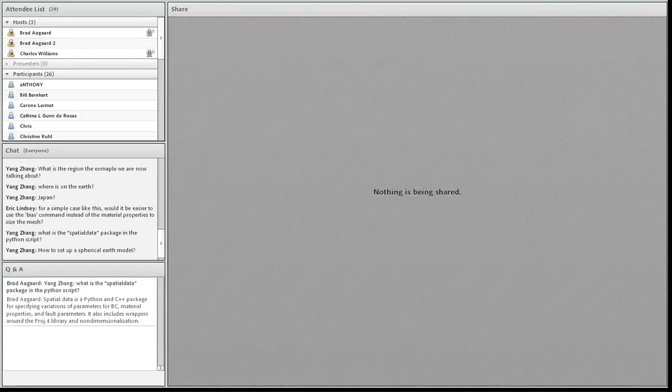And using the Earth-centered, Earth-fixed coordinate system, you can translate from latitude, longitude, height relative to either the geoid or the Earth surface to an Earth-centered, Earth-fixed coordinate system. Generally, we haven't applied Pilot to domains so large that you really had to take into account curvature of the Earth. We've been doing sort of the 1,000-kilometer length scale, where curvature of the Earth doesn't play much of a role.